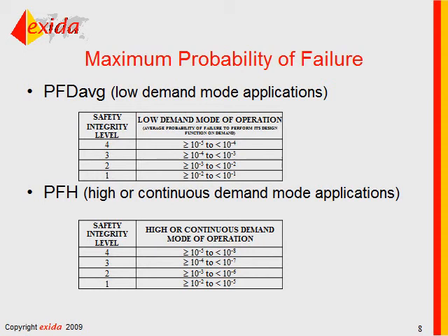If you are able to react when there is a detected failure, then that will be considered a high demand. So there's typically a 10x difference between the worst case diagnostic time interval and the demand interval would be the difference between high and continuous. And of course, you need to look at speed of response of operators as well.